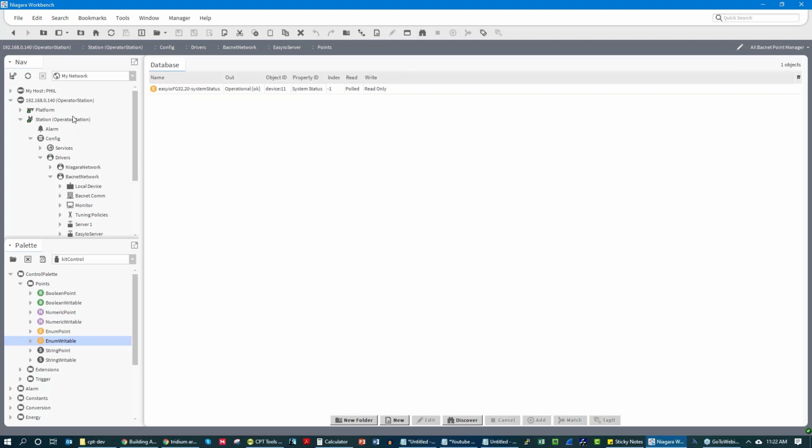So at this point, you should have an understanding of what the four parts of a building automation system are. Those are the servers, the supervisory device, the trunks and field controllers, and the inputs and outputs. You should understand that we utilize software to configure supervisory devices and databases. And we utilize that same software to map in our field controllers and discover our points.